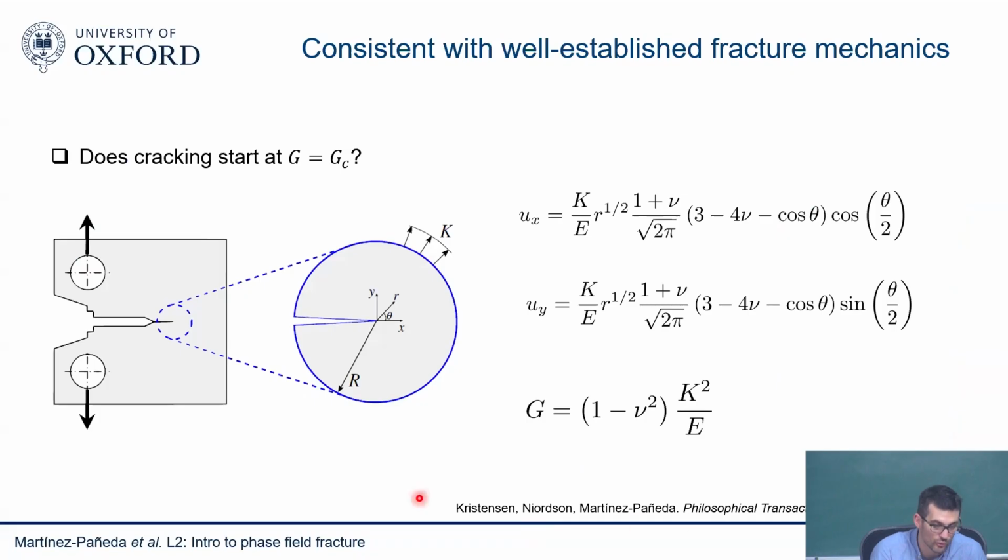So one thing that you can do is, as I told you before, the displacement was related to the stress intensity factor. This is what we call the Williams solution. If I think of a crack tip with a polar coordinate system, r and theta, I can express my displacement field as a function of the stress intensity factor and the coordinates. Which means that what people in fracture mechanics often use is what they call a boundary layer model, and they take a circular model like this one,